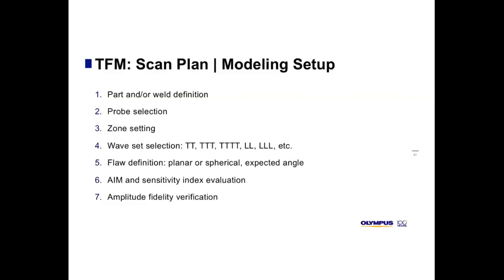And at the end of this webinar, I hope that you will understand the importance of this modeling in a TFM technique or in TFM inspection. As for phase array, we start with the part or the weld definition, then the probe selection. And instead of selecting a sectorial scan or linear scan or compound scan, here we will select a zone. This is what I'm calling the zone setting.